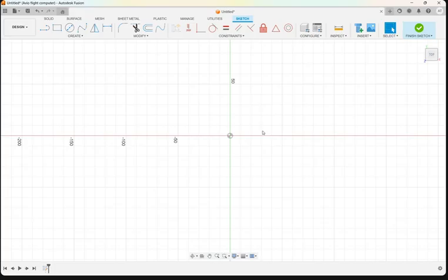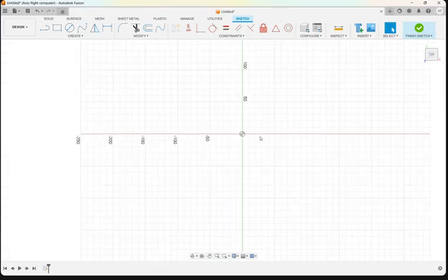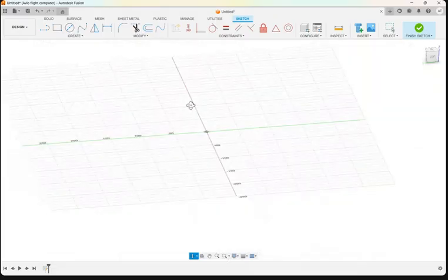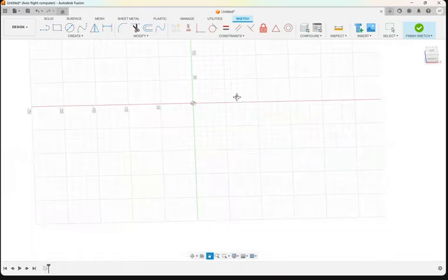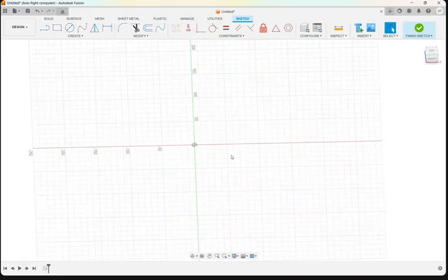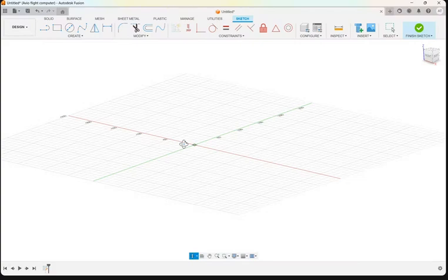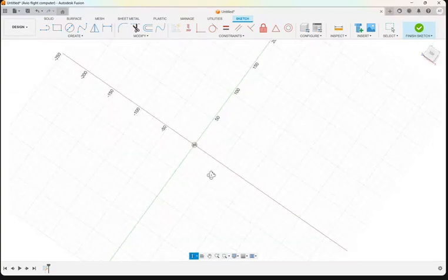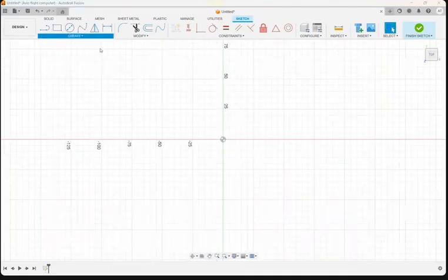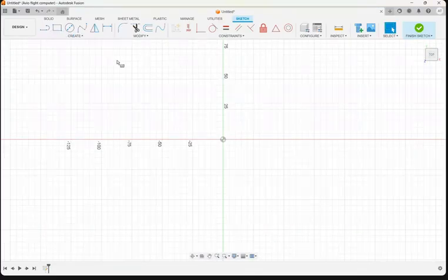If you want to revolve around somewhere, you have to press and hold the shift button and press and hold the scroll wheel. Then you can revolve around. The scroll wheel alone is for moving an object, this full plane, somewhere. If you want to revolve the plane, you have to press and hold the shift button and then revolve around. So we'll start with the normal top plate, and we'll choose the center point rectangle.